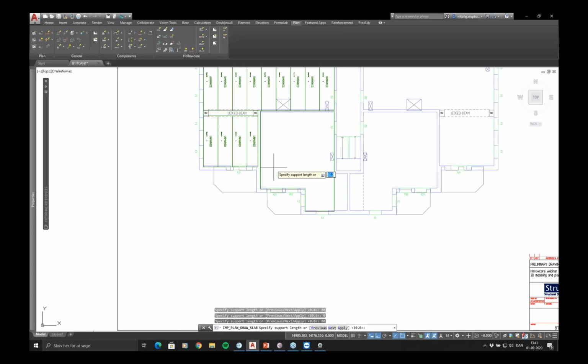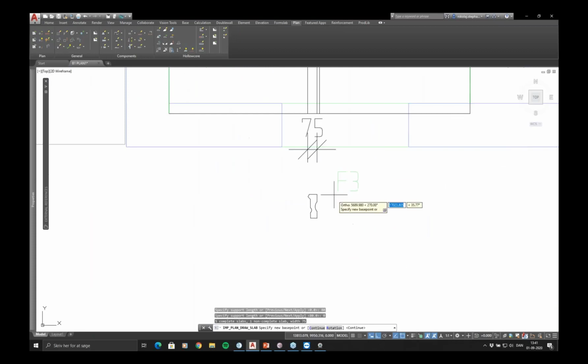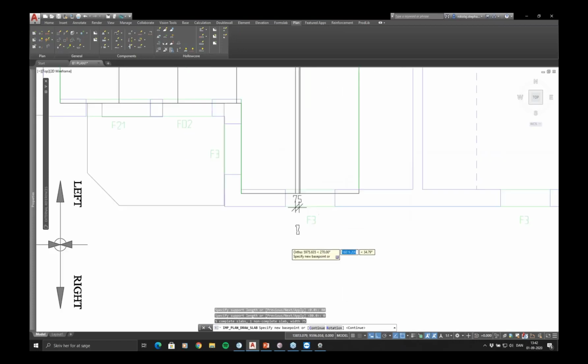So here, when I'm doing these points, I have to guide the software a little bit because it doesn't necessarily know exactly where the elements should be on the walls and so on. So here you can see that this is not good. I can't do a hollow core like this. So basically what you can do is set up rules that won't allow you to cut these small pieces here. And you can see the rule I have not set up here.